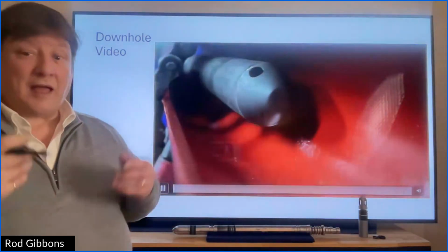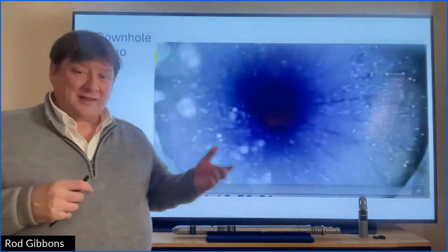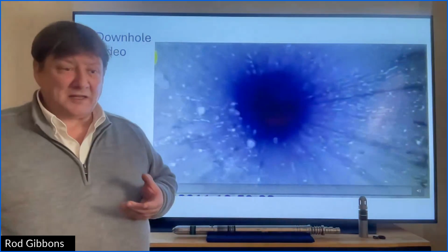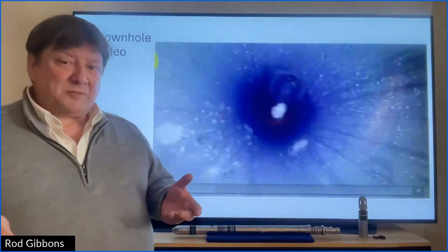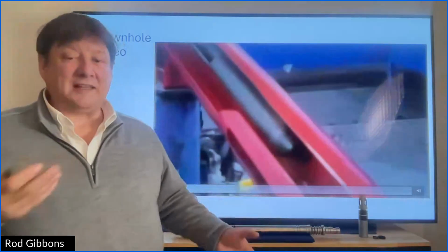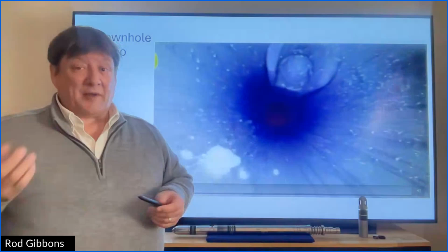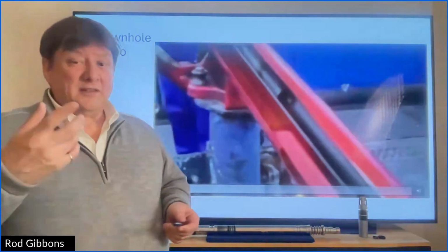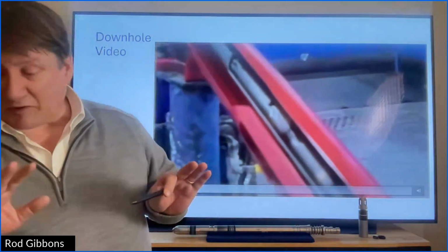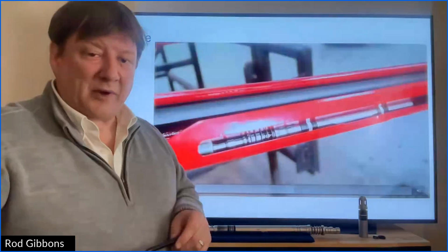Again, if you're comparing gas lift valves to ESPs, if you've run an ESP, then typically you have to pull the completion to get the ESP out and change it out. So from an energy efficiency point of view, this is a much smaller operation, and from a risk point of view, this is actually a lot more lightweight equipment.